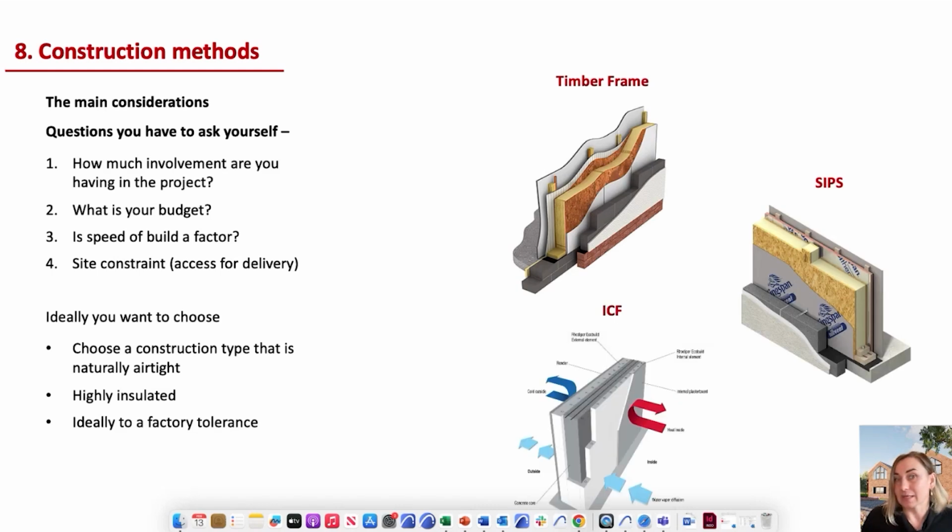So one thing to say here in terms of the construction method suitable for a passive house, I guess, is that you can actually build a passive house with any construction method. There are other aspects of that consideration that are worth mentioning here, but obviously somebody could be looking at block and beam construction because there's availability of contractors who do that in your area, and of course you can do that. It's slightly more challenging when it comes to the detailing, so there are modern methods of construction that have been specifically developed to deal with those aspects of the fabric first approach.